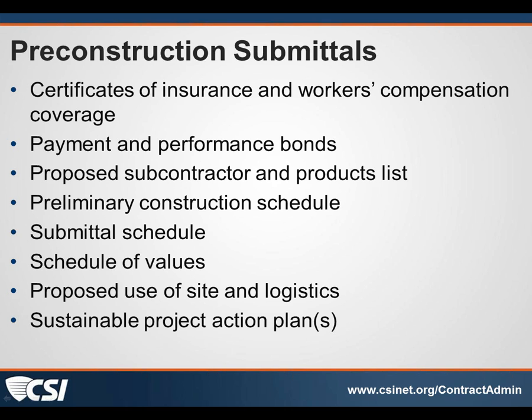Setting a schedule that is attainable, that's doable, that the general contractor is able to pepper out across the early phase of the job so that critical items for construction can get submitted, reviewed, and returned. And if there's agreement between the parties that this schedule is something that we're going to stick to, so that materials can move the project forward, and then allow for things perhaps to be submitted later that aren't so vitally critical to the schedule. So getting this submittal schedule in hand is also important.